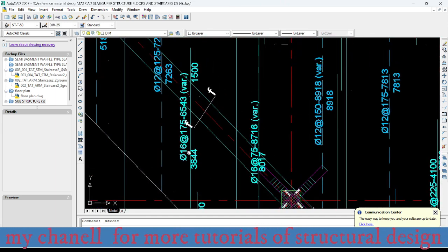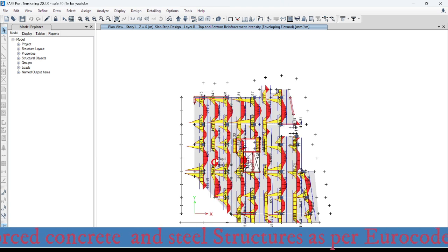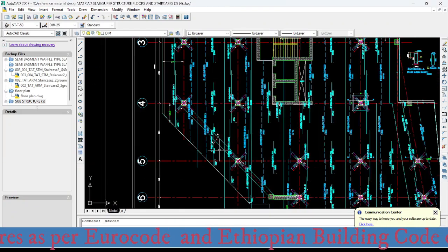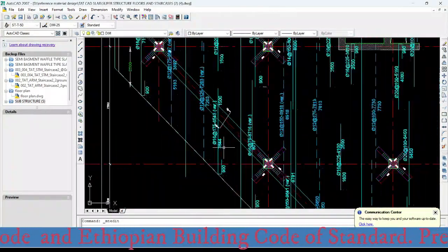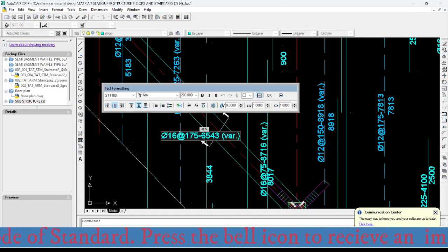And this one also the same. Now let me check it once. Here we don't have any negative reinforcement. 1, 2, 3, 4. So we need to provide at 4 supports. So I can take similar reinforcement detailing here also, that is diameter 12 with a spacing of 200.